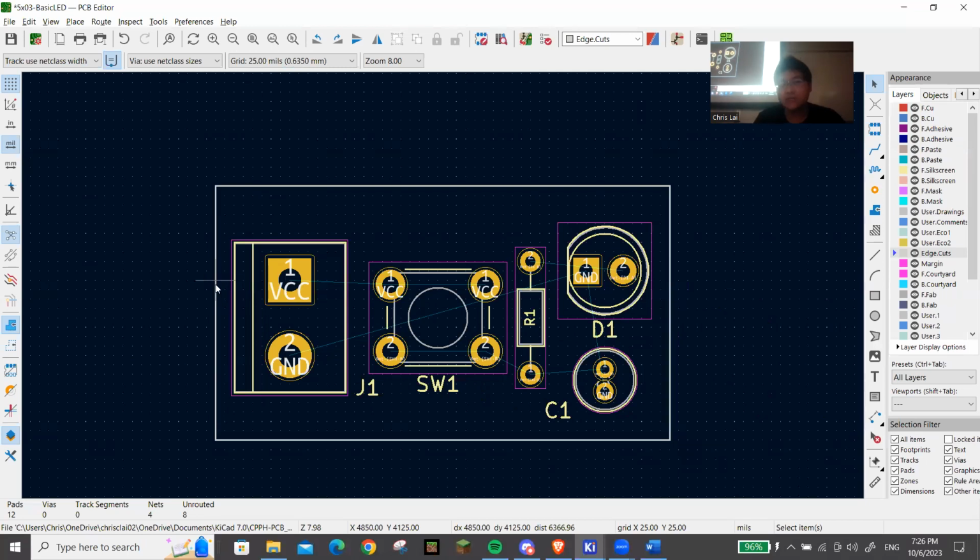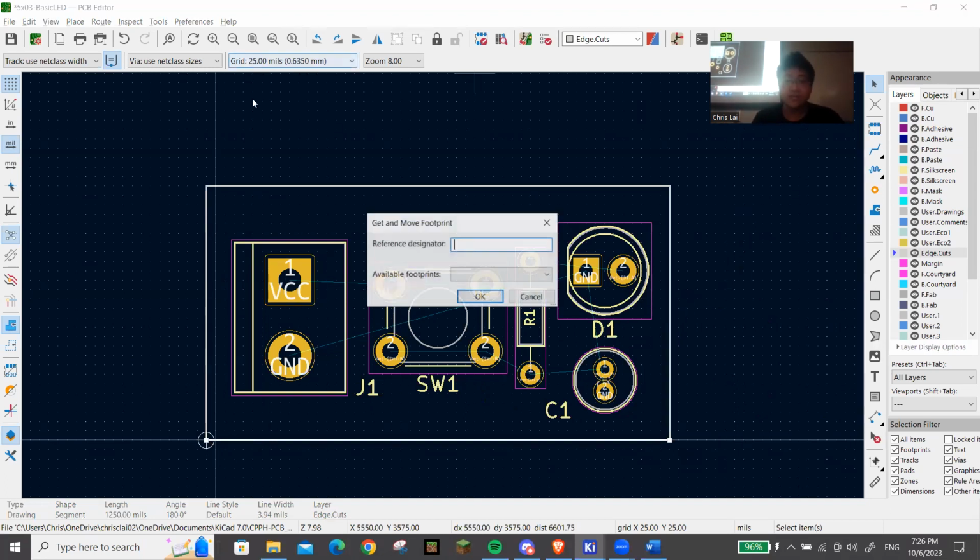So while you guys are getting to this stage, I'm also going to add some textual elements onto the PCB. Half of this is making sure the user doesn't come back and complain at you when they're using it. So especially for things like BlinkyLearn or for our soldering workshops, where maybe less experienced soldering students would put it together, I need to make sure that we have a lot of labels on the PCB telling you how to put the components in. Things like capacitors, things like diodes, they may be polarized, so they only go in one specific direction. Things like the power input has to go in through one direction.